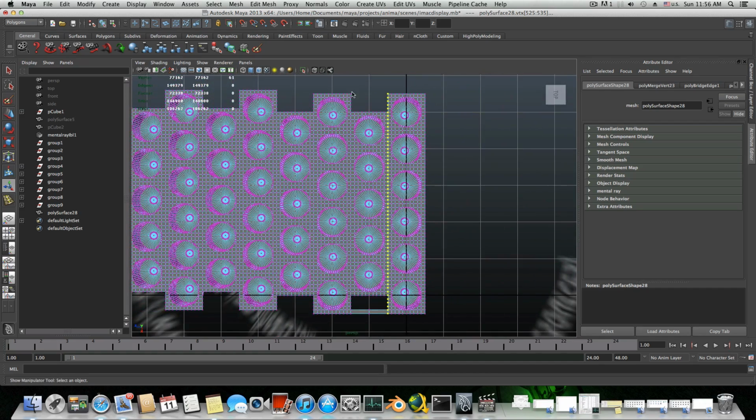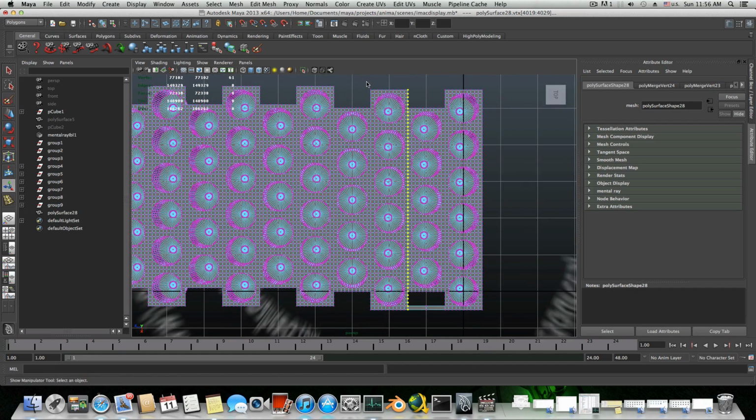Now we will rely on these vertices, and I will press G again. G is the last function you used, and if you're not sure it's done it, go over Edit Mesh and do Merge, and nope, we only want those, and G. You can see here the result is poly merge vertex.